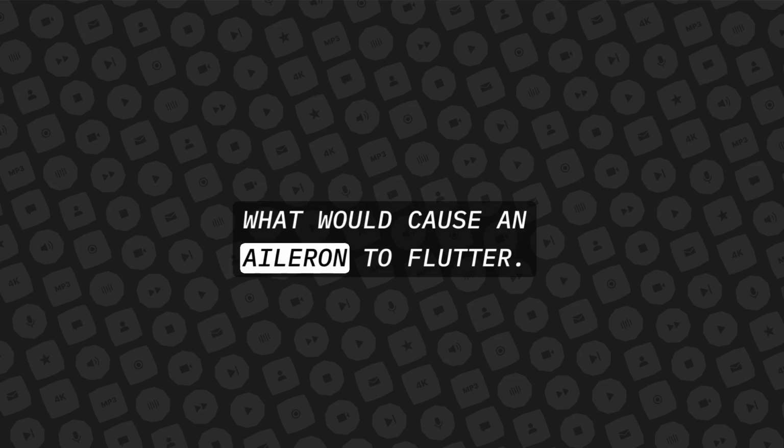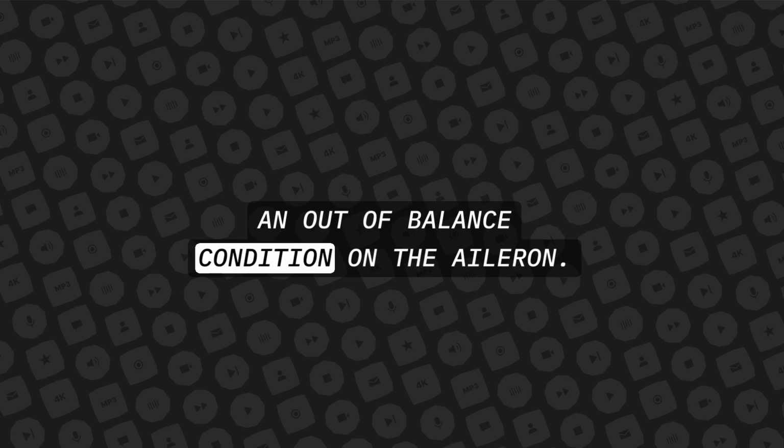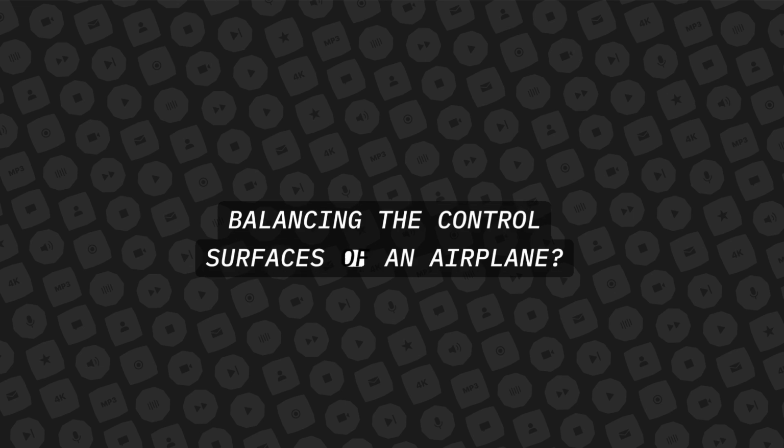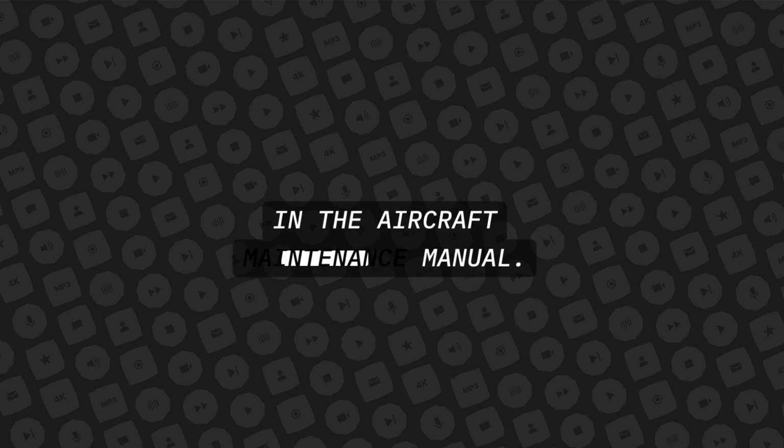What would cause an aileron to flutter? An out of balance condition on the aileron. Where can you find the specifications for balancing the control surfaces of an airplane? In the aircraft maintenance manual.